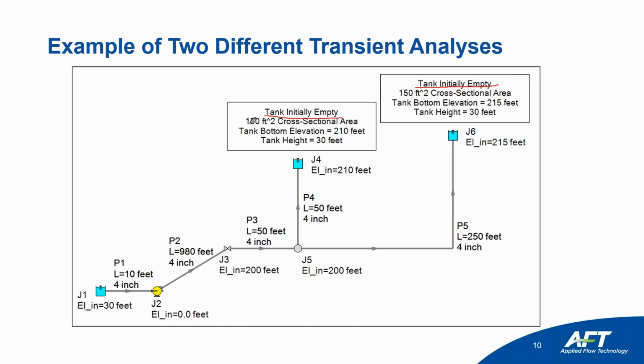I have assumed a 150 square foot cross-sectional area. I can't remember what the diameter of the tanks were off the top of my head. I think either I assumed 20-foot diameter tanks or maybe 10 feet. You can do the math. It just asks you for what the cross-sectional area of your tanks are if you're using Fathom XTS.